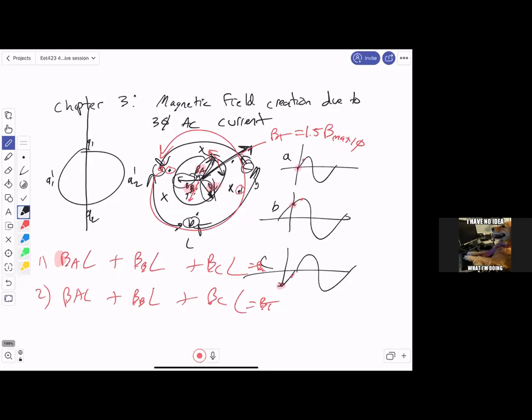And so this motor electrically will only take 180 degrees of mechanical rotation to get 360 degrees of electrical rotation, because as this magnetic field is rotating, it's inducing current flow in that winding. Well, that same current flow is going to happen 180 mechanical degrees apart. So that's how I get the 360 there.